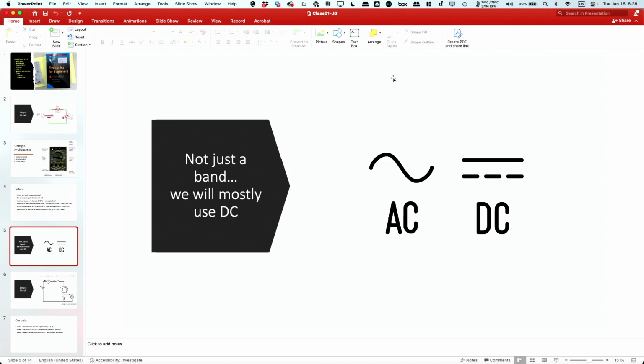Then you pick up a new problem with modern cameras, right? So a film camera exposes the film with just the light that hit the film, right? Electronic camera, light hits the sensor, but you read out this line, then this line, then this line, then this line. And if the image has changed in the time that you're reading the lines, you can get what's called a rolling shutter effect. Look up rolling shutter in propeller aircraft sometime.